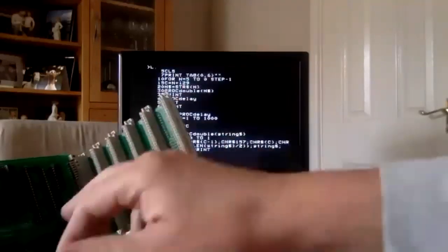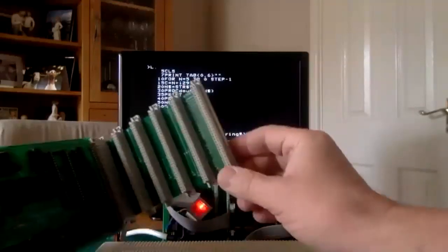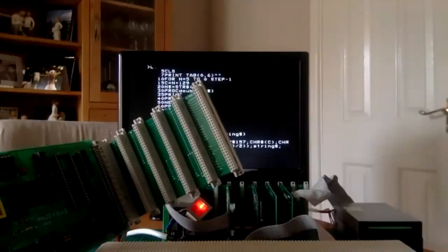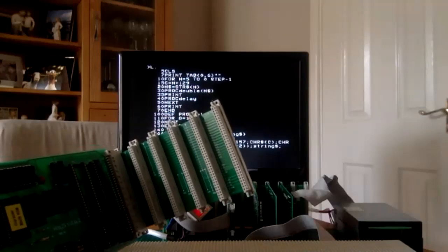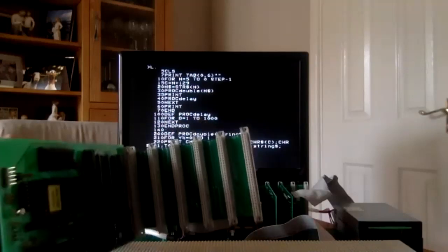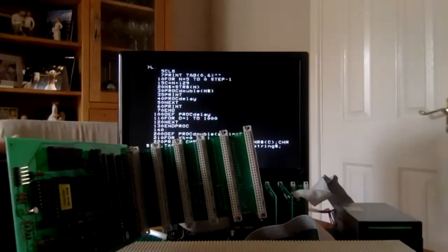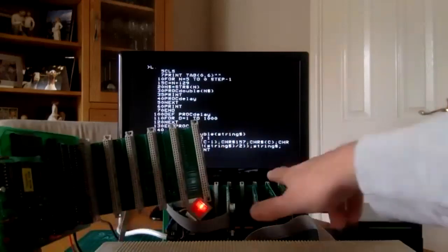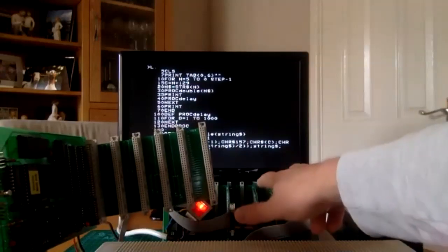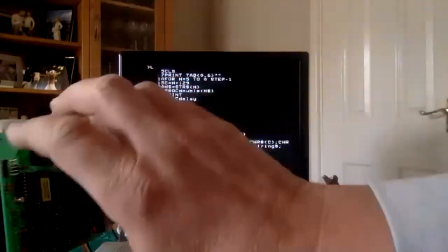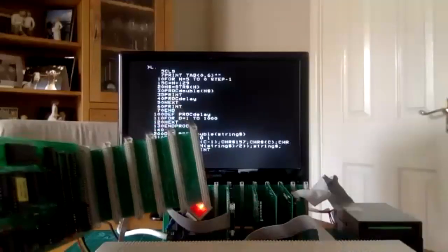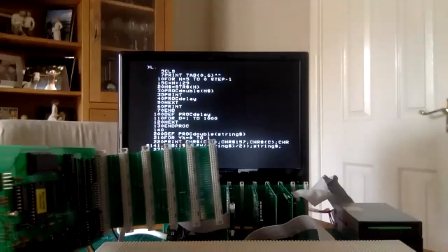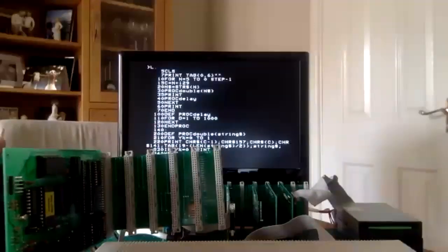So I would be demonstrating the System 5 today, but the chip, the 6845 or the 68B45, I was hoping it to be, turned out to be a 1 megahertz version versus a 2 that I needed. So this is as much of the System 5 demo as we're getting today. But basically, the RAM board and the floppy disk controller go into this system. I'll get an 80 by 25 display, very similar looking to Node 0, and an upgraded 2 megahertz CPU.